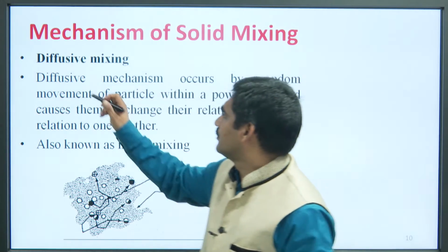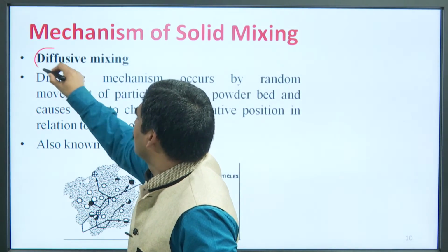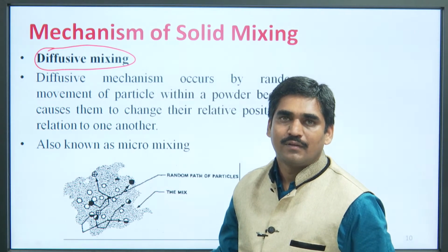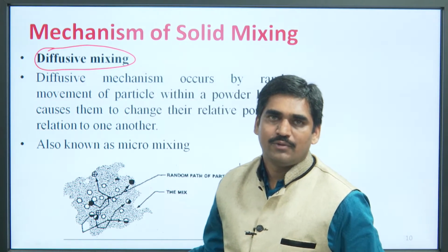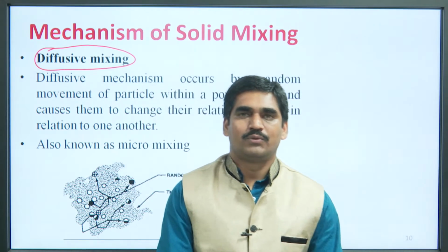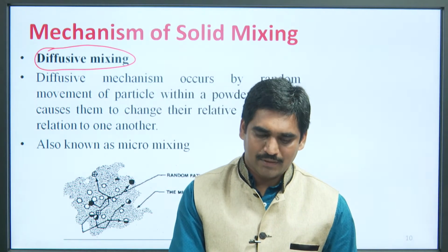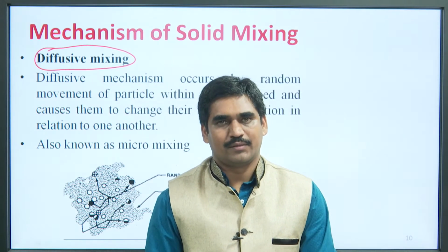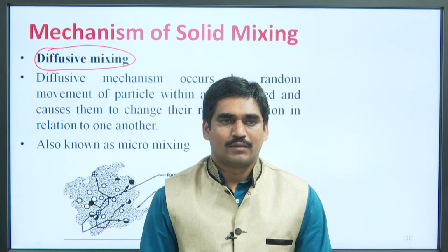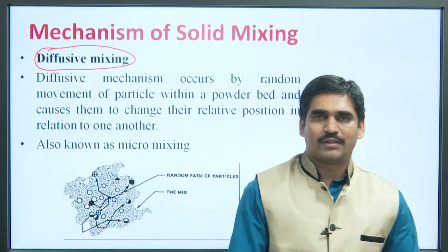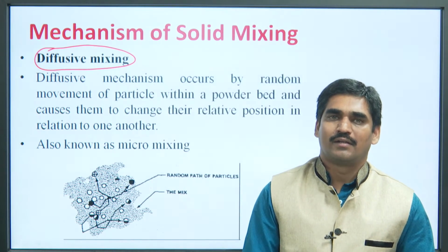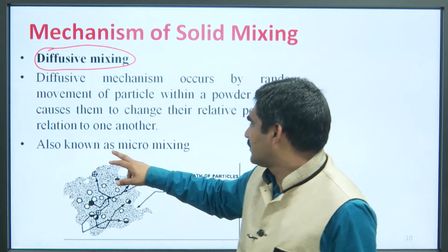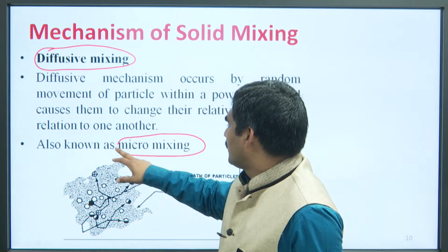Third mechanism is diffusive mixing. Diffusive mechanism occurs by random movement of particles within a powder bed, and it causes them to change their relative position in relation to one another. This type of mixing is also known as micro mixing.